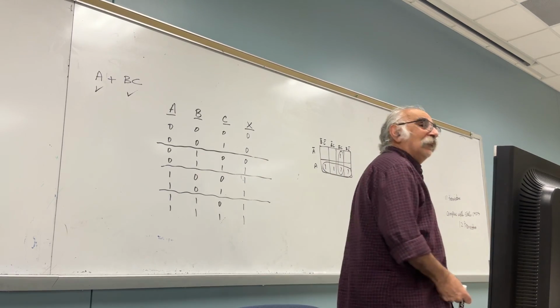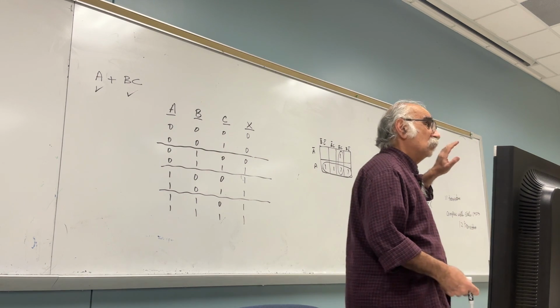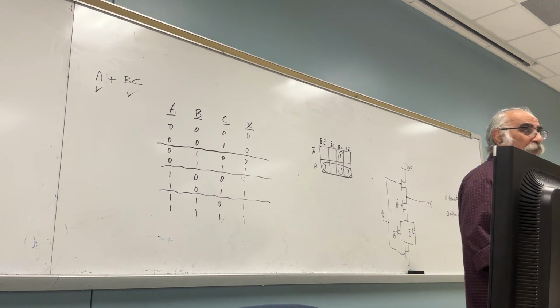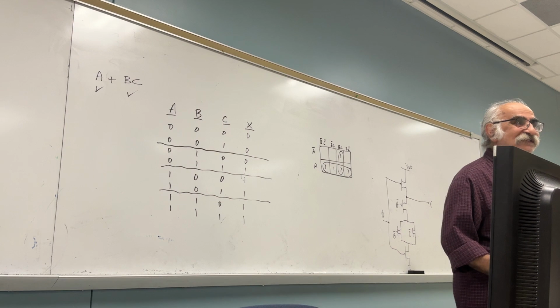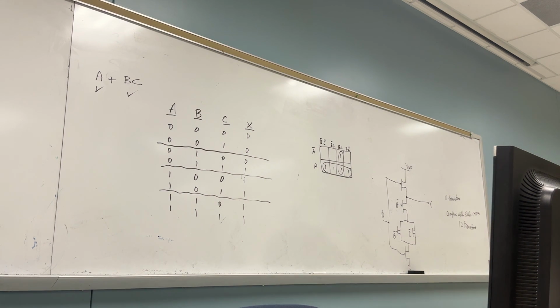Now, keep in mind, I don't want you to ever think that the dynamic logic is replacing the static logic. It's the other way around. The static logic is the one that is robust and the one that is used the most. Dynamic logic, as we'll see, most of the time you use it for memory, DRAM, dynamic RAM, clear? Or somewhat specialized electronic circuits that require less area. Did you get it or not? Okay, good.